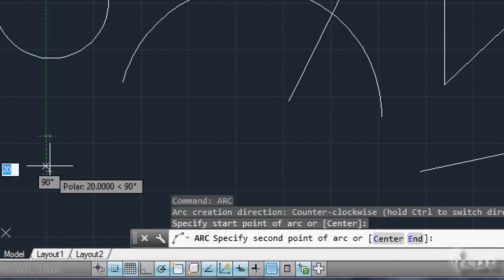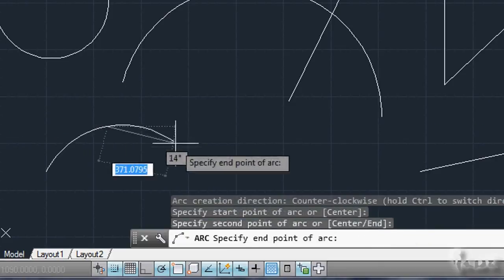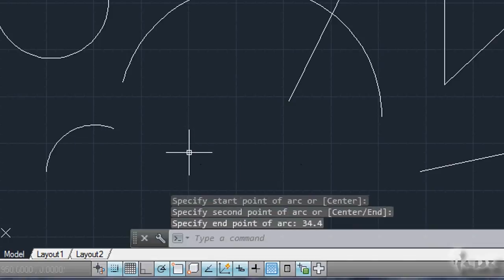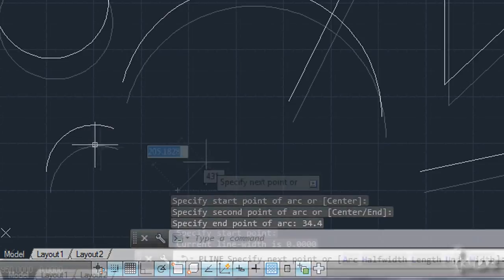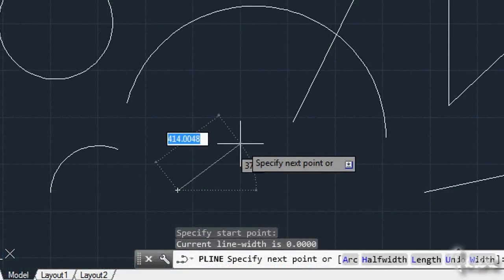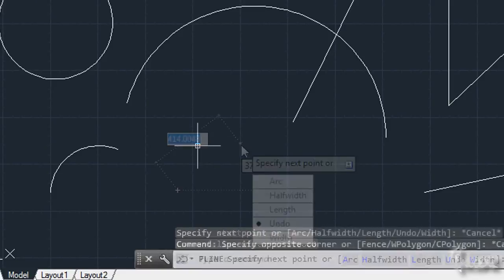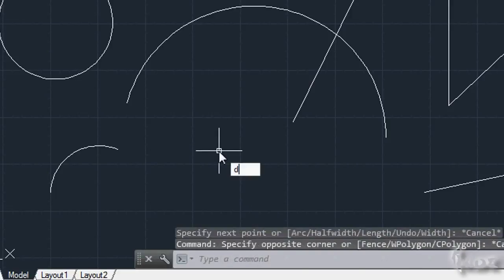The white slot can be used to enter precise numbers too, which is fundamental for professional projects. Instead of setting a point or distance using the pointer, you can enter your precise value. Moreover, commands can be chosen using the down arrow key. Choose the command you prefer and then press Enter. You can use this slot to do anything without using the buttons above.